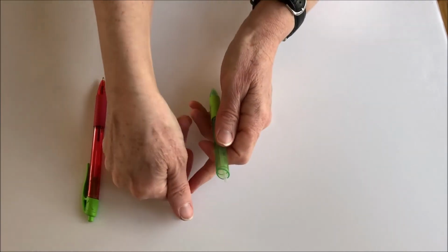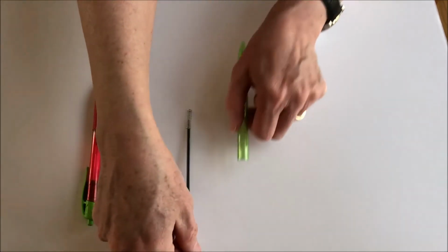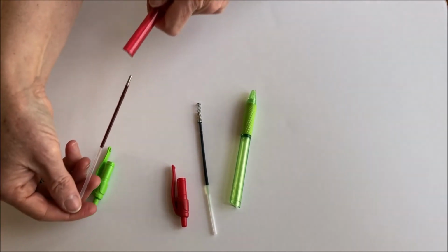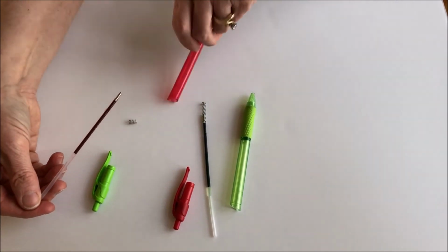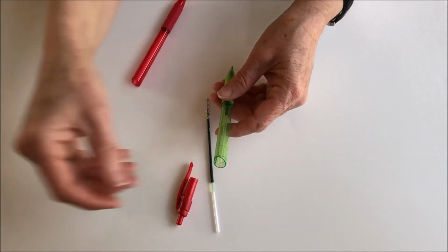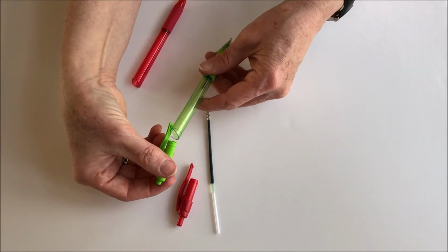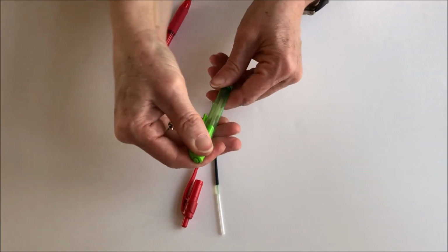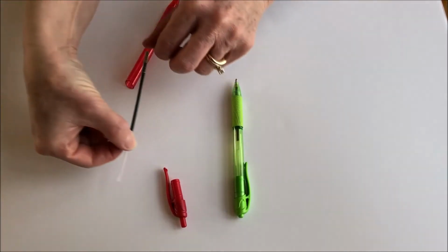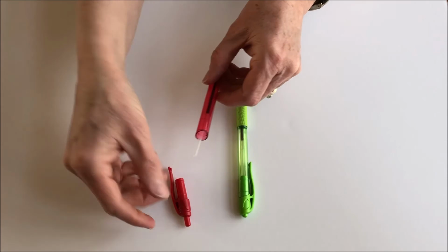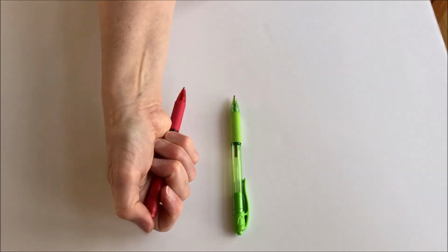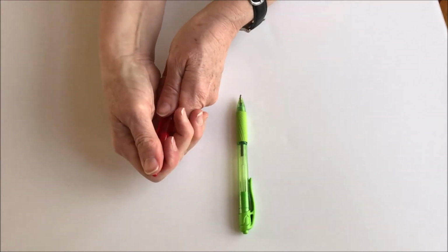So now I'm going to take another sub-assembly, which is this centerpiece with the ink. So I will take the centerpiece with the ink out for both of them, and I'm going to put the, it's a sub-assembly, it's got a spring there. I'm going to put the centerpiece with the ink into the green pen from the non-working pen, from the red pen, and put that together. And it's broken now. And I'm going to take the centerpiece with the ink from the green working pen and put it into the red pen. And it works. So the problem followed that centerpiece with the ink.